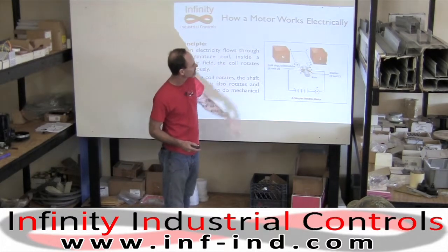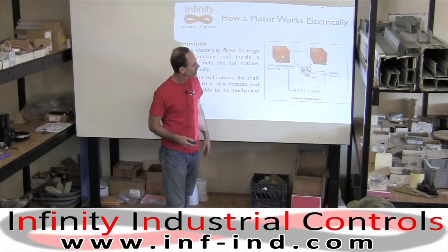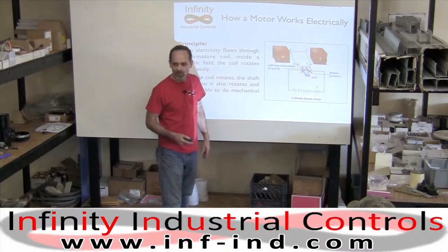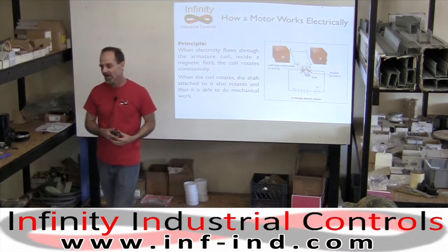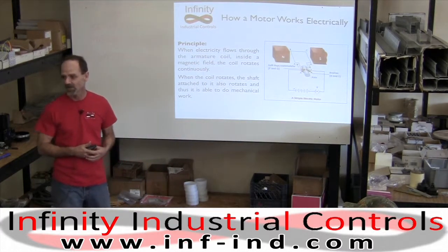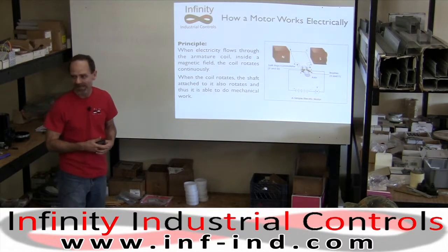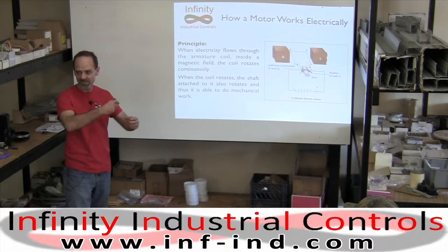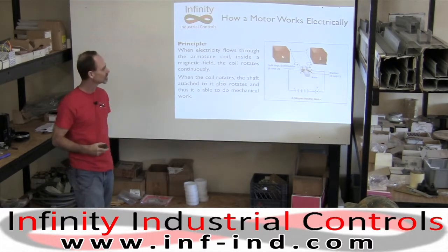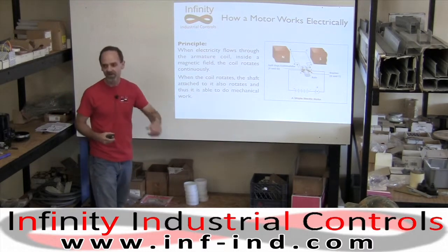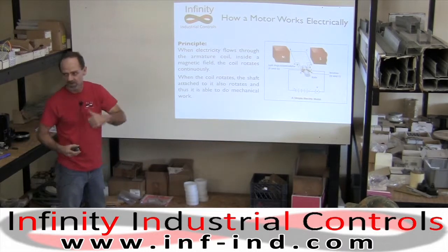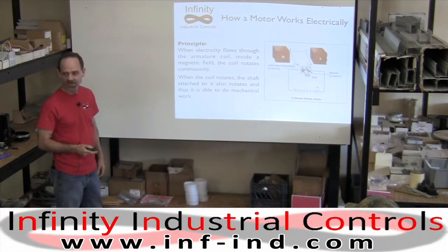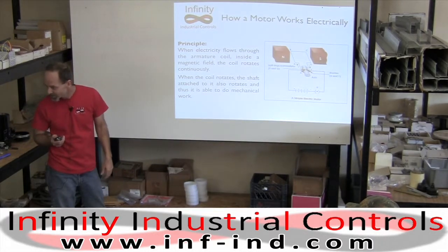A lot of times in DC motors, the load will actually pull it faster than the motor can go, and it's actually acting as a brake. If the load actually wants to pull it, it's doing a reverse torque thing, and it'll actually regenerate back to the line. Your little hybrid cars do that too.